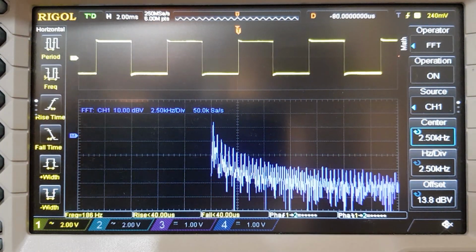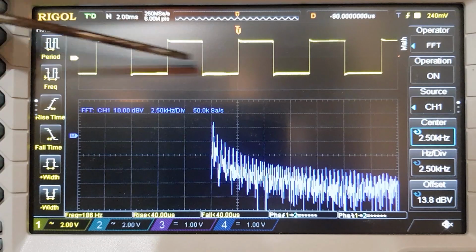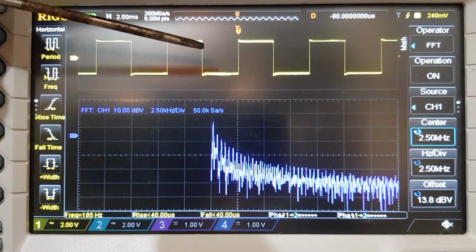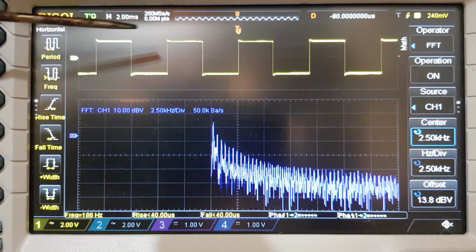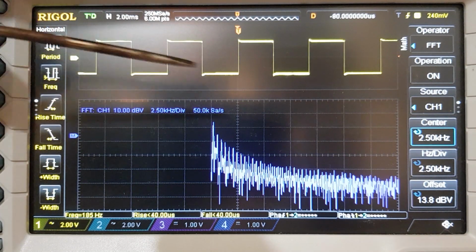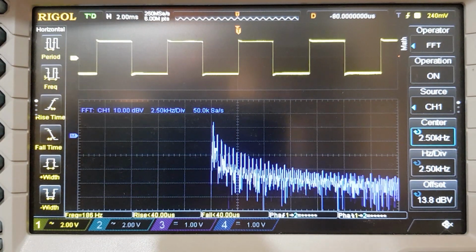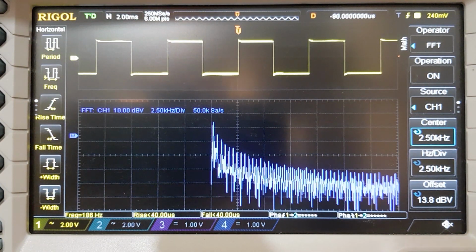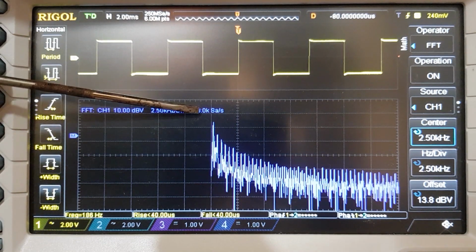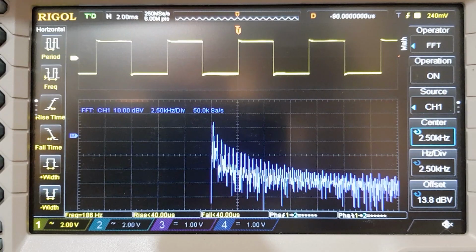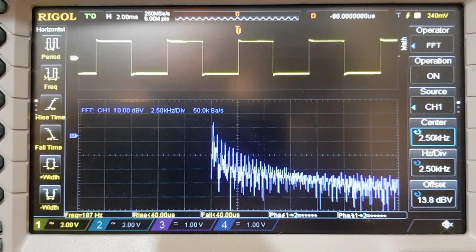This view we're probably somewhat familiar with, kind of a sound wave. This is what different waves look like. Different things have different shapes on the oscilloscope, and you'll come to learn them all. But this view is slightly more abstract, but actually a lot more useful for what we're doing. So we can see this fundamental frequency here, which is the lowest and strongest frequency. Strongest because it's the biggest in amplitude, it's the highest one on this plot. And that's what tells us what note it is.